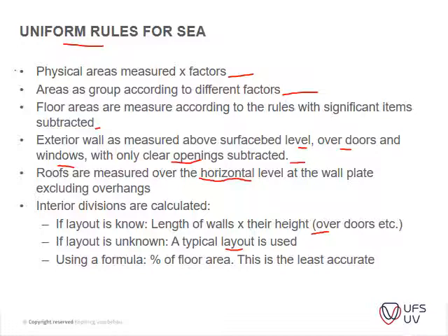Okay. You can see this method can be used if the interior layout is not given. You can actually use standard layouts of previous buildings to get the different areas of your interior walls, for instance. So using a formula, the percentage of the floor areas, this is the least accurate.